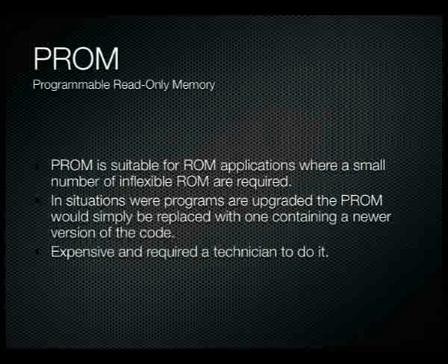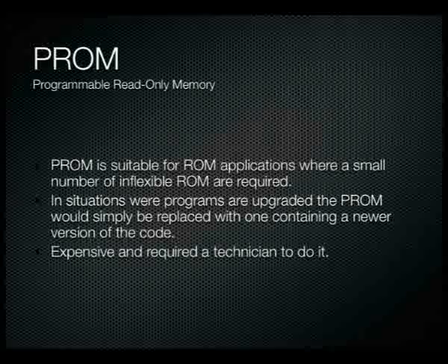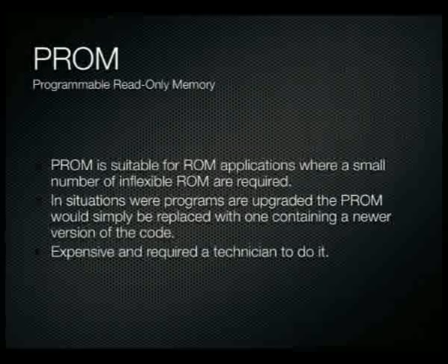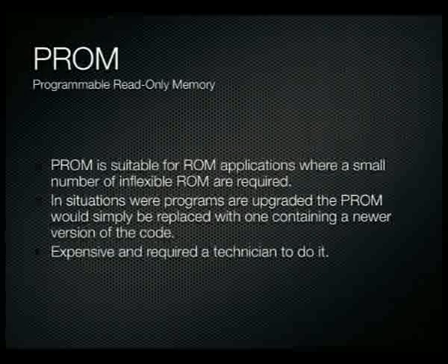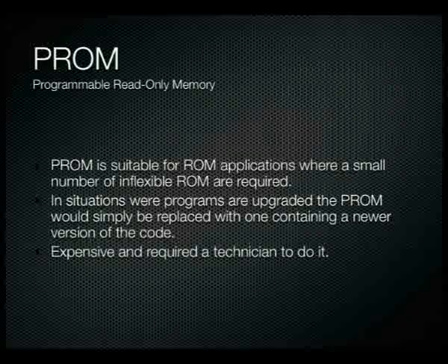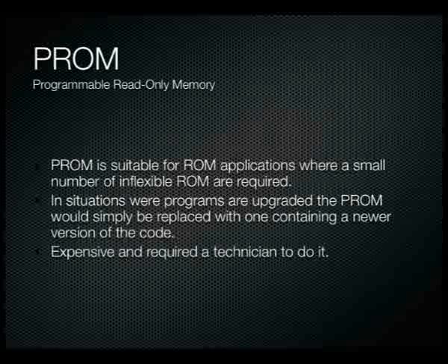And the other disadvantage is you actually need a technician to do it, because you need someone with a bit of skill to be able to tear the device apart, find where that PROM chip is, remove that PROM chip, burn up a new PROM chip, and put that new PROM chip in its place. So it requires a bit of expertise and basically requires a technician to do it. So it's quite expensive. I guess you could think of a PROM in the same way that you might think of a CDR. When you burn a CD, you make a mistake, you've got a brand new coaster for your coffee mug, but then you've got to get another CD and burn it again. So a PROM is very similar to a CD.